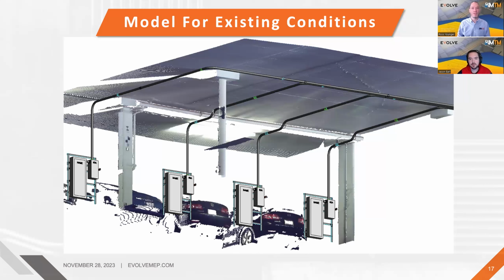Yeah. That's generally referred to as decimation, decimating the point cloud, and it's certainly very common to retain that max size point cloud. But if it's a 120 gigabyte point cloud and you're looking to collaborate around that, it might not be feasible. So you could decimate down to 1/5 the number of points and work off that model, and then know that you have a denser model in your back pocket if you need to get that higher level of detail.